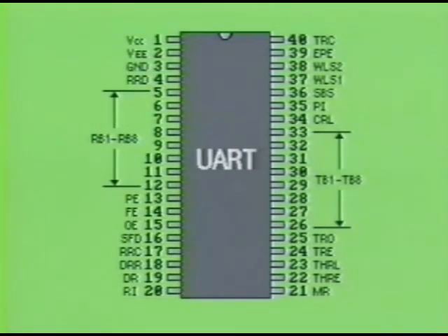Basically, the UART makes the task of receiving and transmitting data in serial form easier for the processor. Most universal asynchronous receiver-transmitter ICs are capable of being programmed by the end user to determine the word length, baud rate, parity type, even or odd, parity inhibit, and the stop bit length. The UART also provides 6 status flags. These are transmission complete, buffer register transfer complete, received data, parity error, framing error, and overrun error.